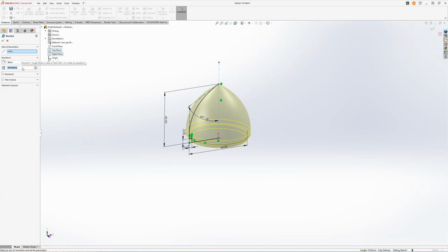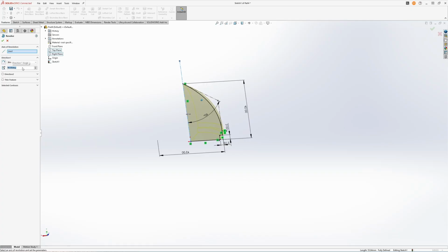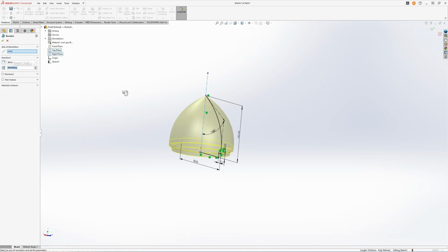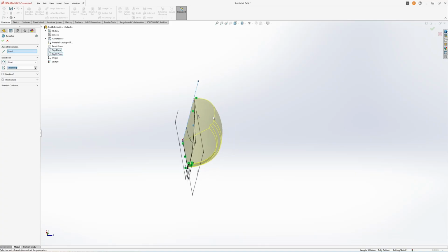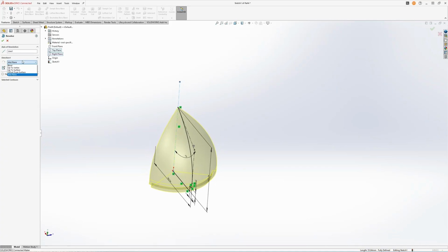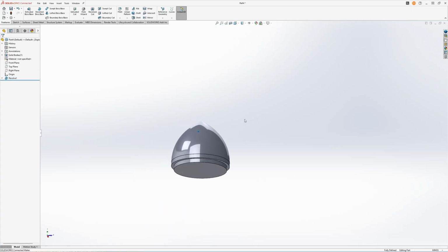And so here you can define how far it should revolve. Do you want 180 degrees, 90, and so on, which you can use for different purposes. Obviously for this case we want 360. I'll just show you, if we do 120 for instance, it'll take 120 from the plane and then around, but you can also do mid-plane for instance. Now it does 120 around that middle. That can also be useful in some situations, but we'll just select blind and 360 degrees. So there we have it.